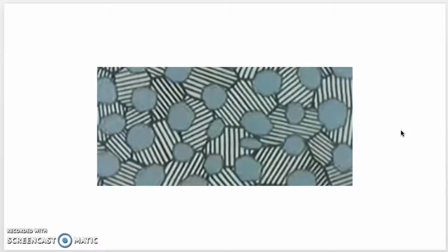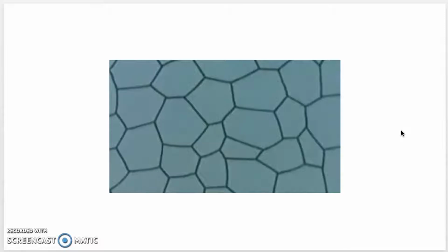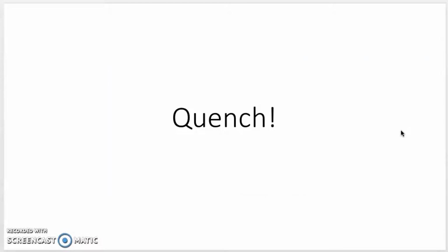The austenite phase will kind of take over the piece of metal, and it'll come out from these grain boundaries and continue to grow until it has completely taken over the piece of metal. And then we're going to quench that piece of metal very rapidly, usually in a large pool of water. By doing this, we make this needle-like structure in our steel, which is extremely strong, but it is also very brittle, and the brittleness is not very desirable.